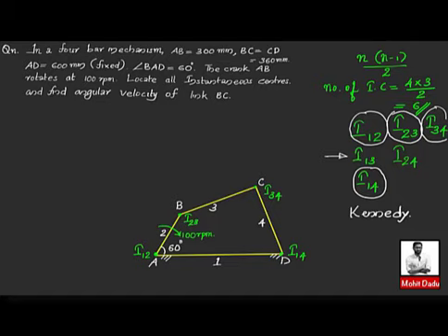So here you are having the instantaneous centers I12 and I23. Out of this, the common number is 2. So out of I12 and I23, if 2 is going, then you are having 1 and 3 remaining. So you are having 3 bodies, 1, 2 and 3, which are having relative motion. Then I12, I23, and the third, that is I13, will be lying on this same straight line.